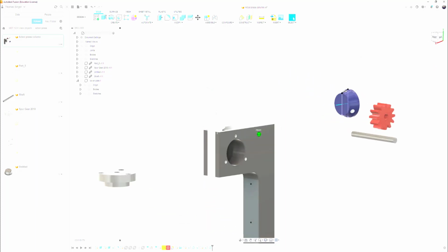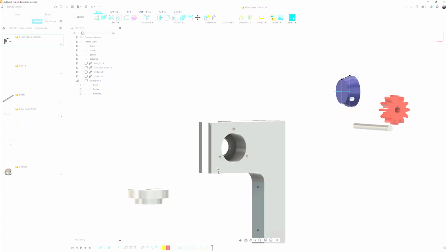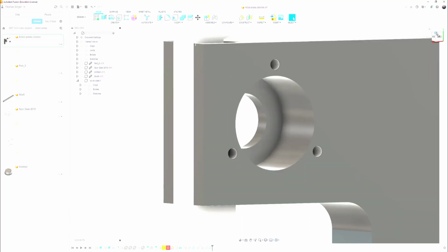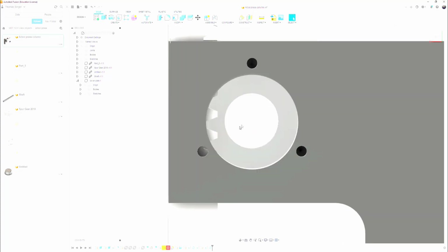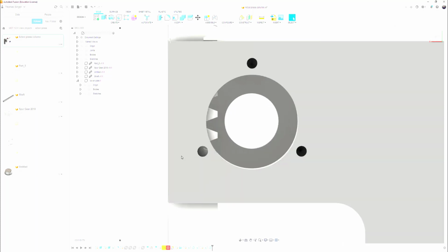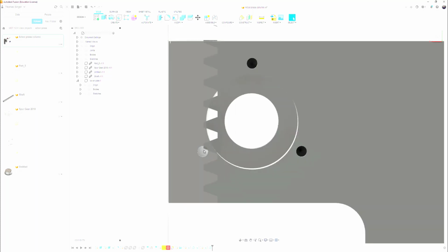So you notice that 1/2 inch, where's that 1/2 inch? Well, that 1/2 inch actually goes all the way to the rack. You can see the rack inside here. So be aware that you can't go beyond that 1/2 inch. If we went beyond the 1/2 inch, you'd actually see the point on the rack that it would fail on that particular process.